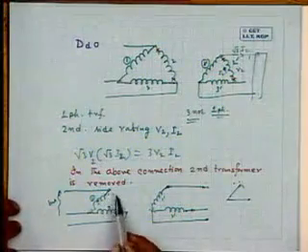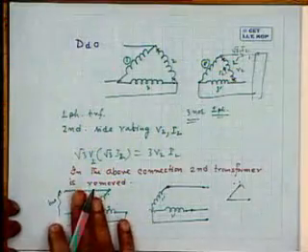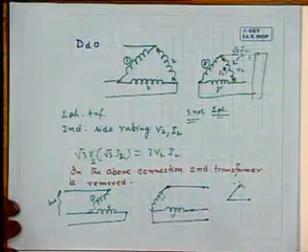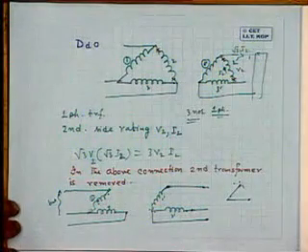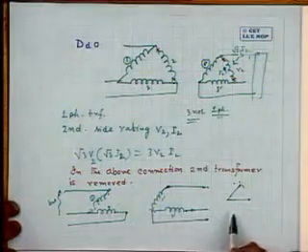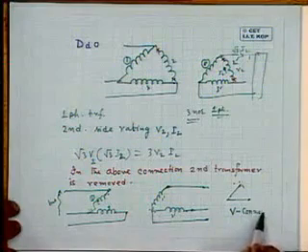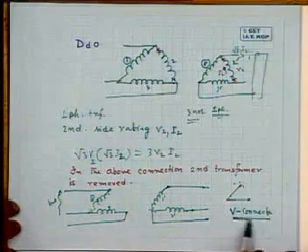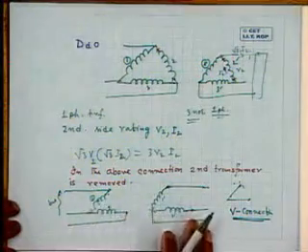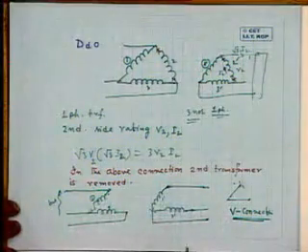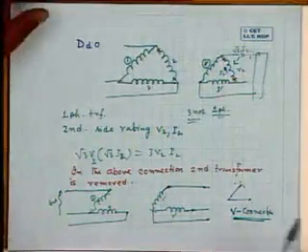But a slight trick like this also shows that a balanced three-phase voltage can be transformed to another level by using only 2 single-phase transformers. And this connection is called V connection, very popular, widely used. It looks like a V, not delta-delta, star-delta, the conventional connection. It is V connection.